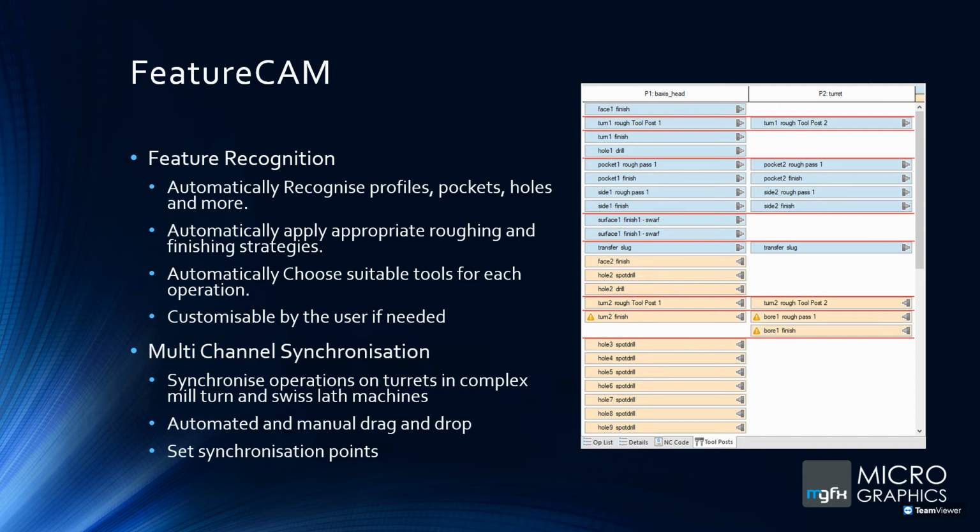If there wasn't synchronization, let's say pocket 1 rough pass, those 4 operations from there down to side 1 finish would have to happen. The part would turn around, and then the next 4 to the right would have to be done. So synchronization saves a lot of time.